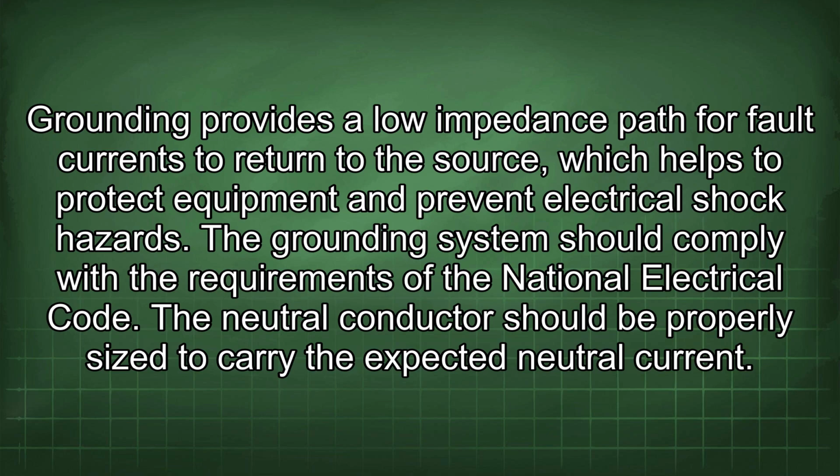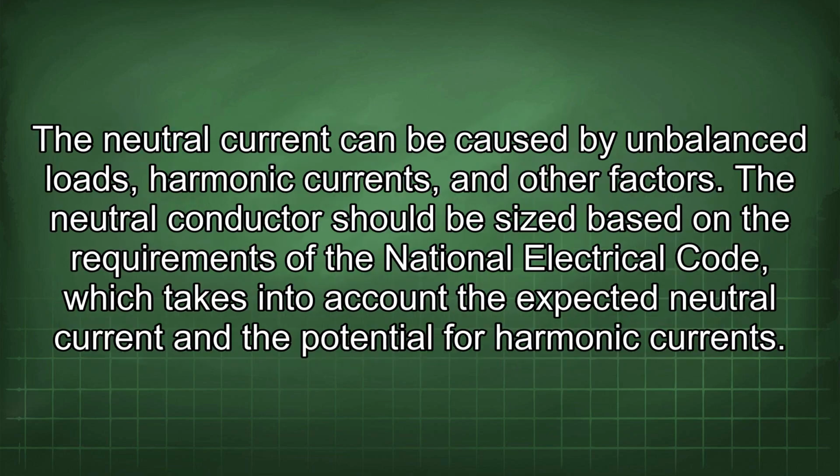The neutral conductor should be properly sized to carry the expected neutral current. The neutral current can be caused by unbalanced loads, harmonic currents, and other factors. The neutral conductor should be sized based on the requirements of the National Electrical Code, which takes into account the expected neutral current and the potential for harmonic currents.